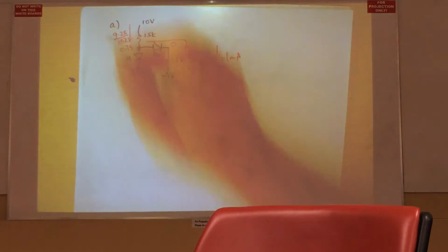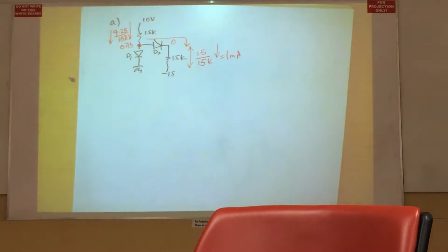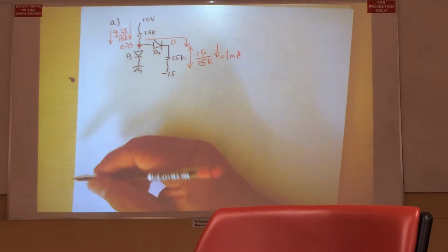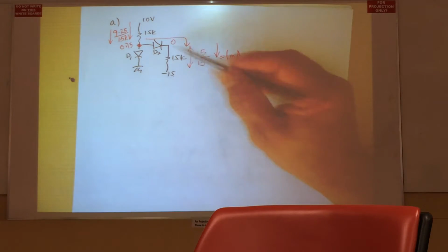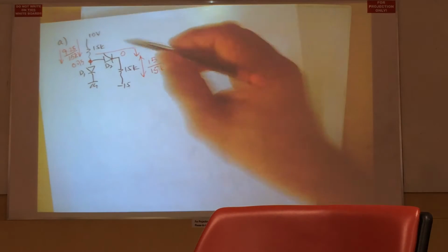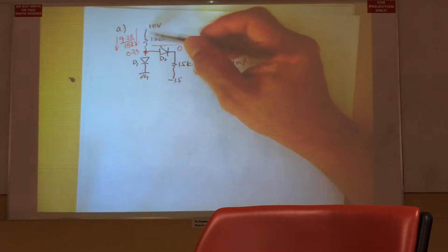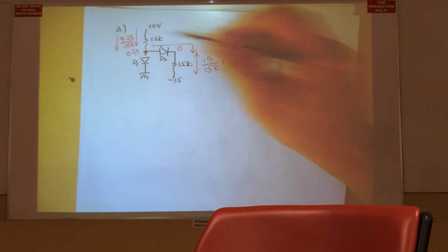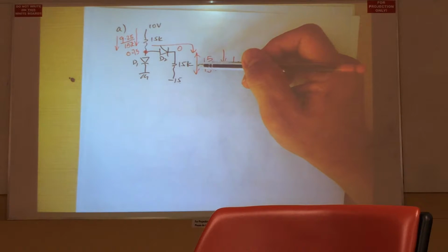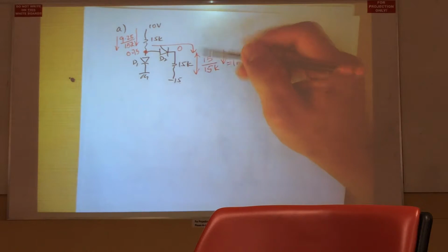So this current that's flowing is less than 2/3 of a milliampere, probably about 0.6 milliamp. And the current that's flowing through the lower branch here is 1 milliamp. So we need to supplement, because this current from the top is less than the current that's going to the negative supply. So we need to supplement some current from another branch.